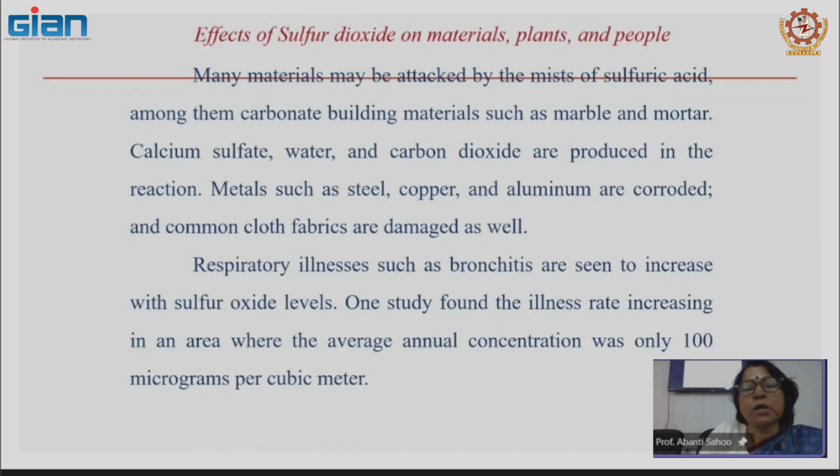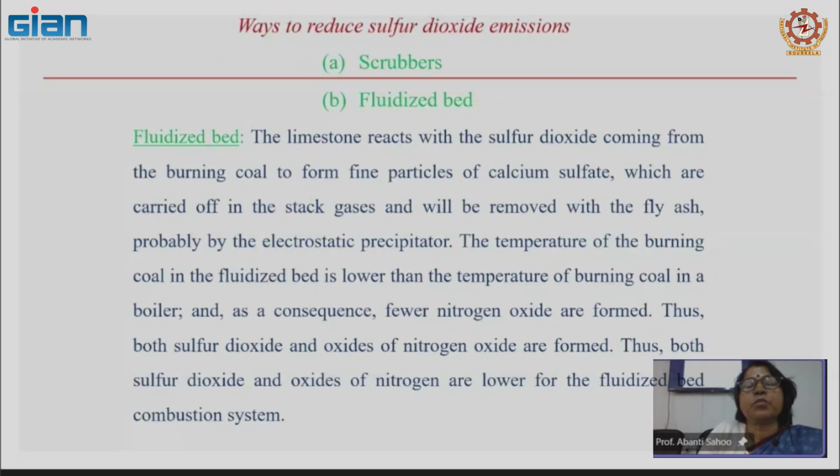Or we can carry out the reactions otherwise. Let me refer to an experiment which we conducted in our lab, in 2015 or so, using scrubbers and the fluidized bed for sulfur dioxide. Limestone reacts with the sulfur dioxide coming from burning the coal, forming fine particles of calcium sulphate, which can be carried up in the stack gas also.